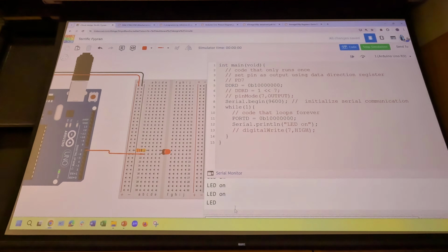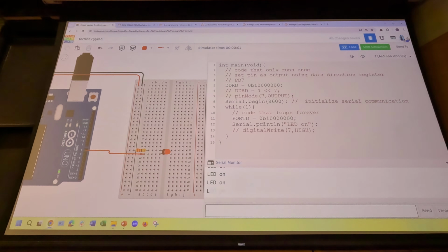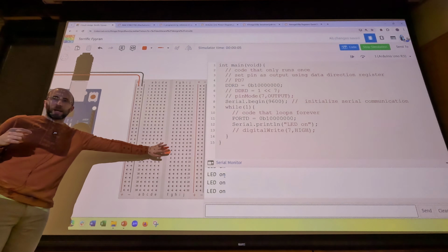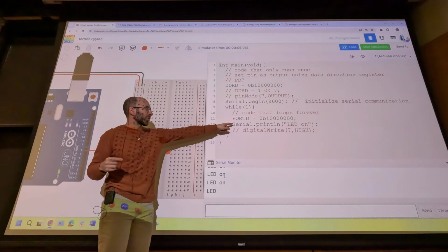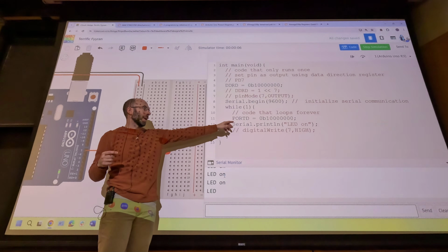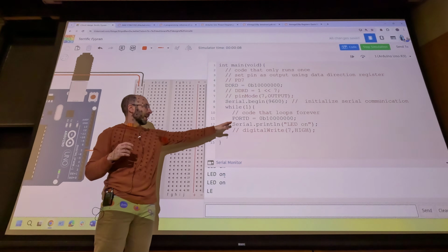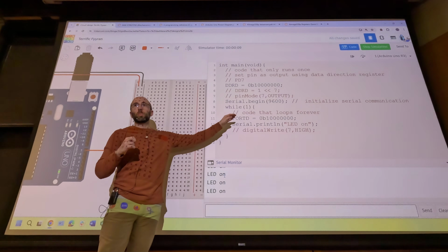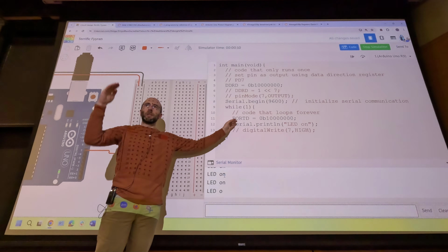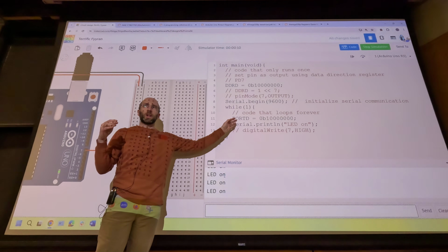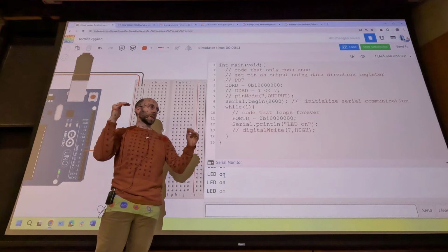Okay. So now, if I run this and open the serial monitor, I put that print inside my loop, so now it's repeatedly printing LED on, right? That at least starts to help you differentiate. Say my LED wasn't lighting up, I can look at this and go, okay, I at least know my code is getting there. So maybe I have the wrong resistor, maybe I have my LED wired wrong. This gets more important when we get to if statements, when you have an if-else statement with 2 different conditions and it's not clear if the conditions are being triggered.